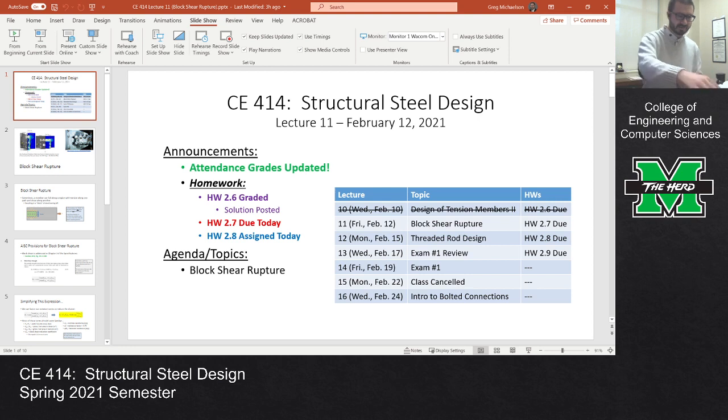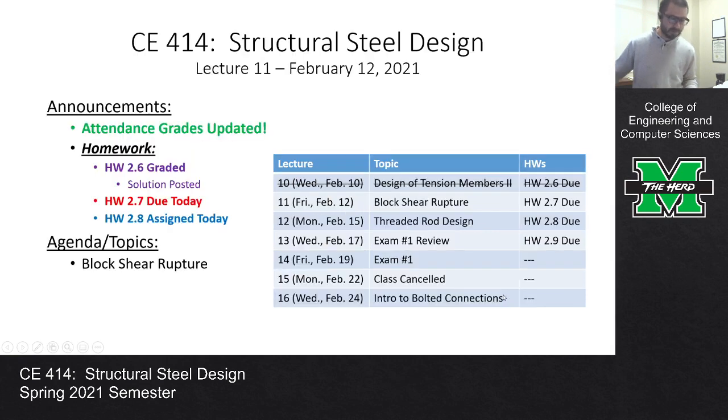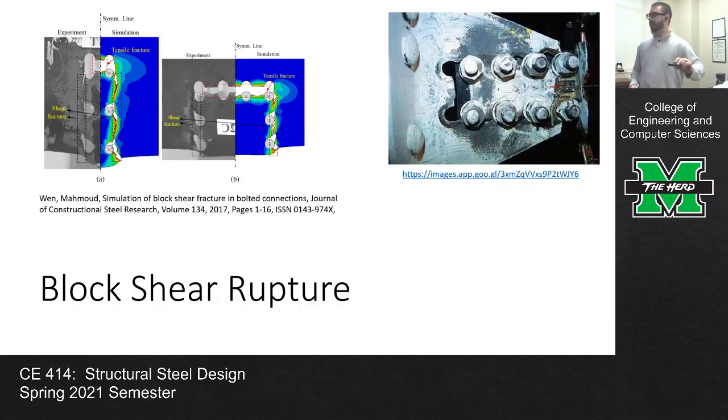All right, we're good. Okay, I want to talk to you a little bit about block shear because this is an interesting one. I'm going to show you a picture of it in real life and some cool models here because this is a unique one. This is something that we haven't talked about yet, and to be clear, block shear rupture is not something that you design for, but it is something that can happen.